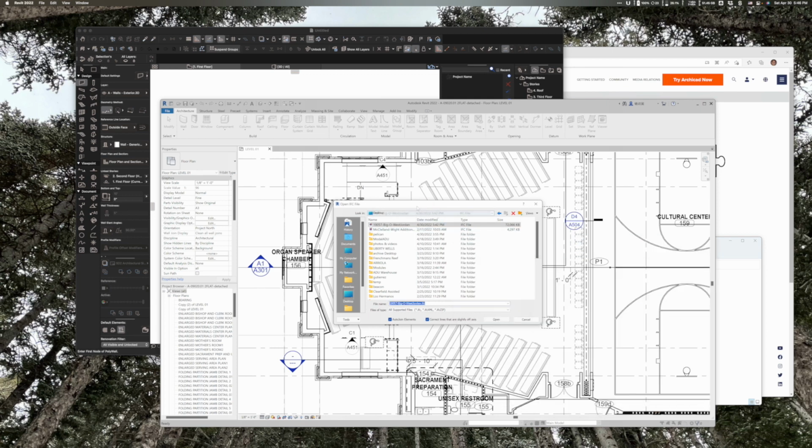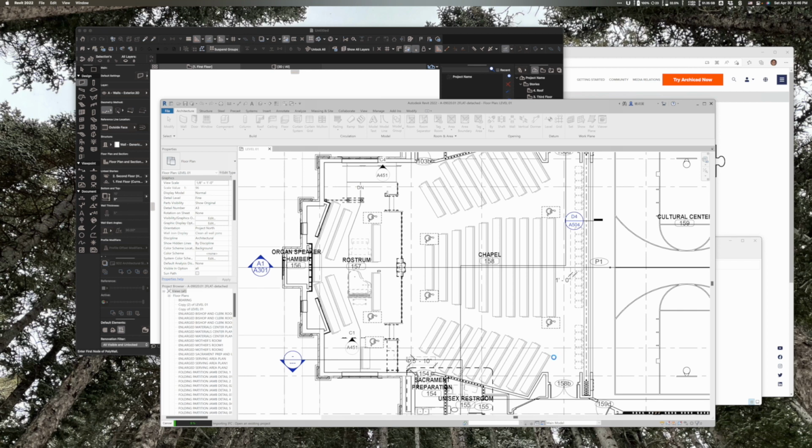Okay. Once I've done that, then I can go back to computer within the Revit dialog. And so this is just an error that seems to be happening with Windows on Parallels. It's not allowing me to access any Mac drives through Revit. I can only do it through the Windows folder, so I have to take the file and then copy it into a location that is only on the Windows portion of the drive. And then once I've done that, then I can get to this IFC file, click Open, and it's going to start opening up the file.